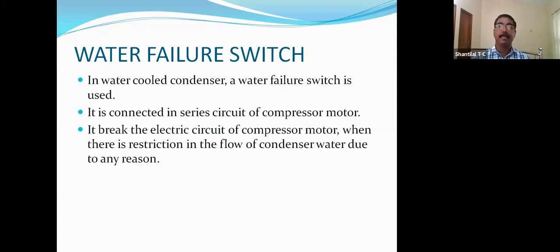That means the water cooled condenser requires water, and that pressure is acting on the bellow, and the contact points are connected in series with the compressor motor in the water failure switch. Due to any reason, if water is reduced in the water cooled condenser, the pressure in this switch will be reduced. When pressure is reduced, the bellow will contract, open the contact points and switch off the motor. This water failure switch is working similar to an LP cutout.